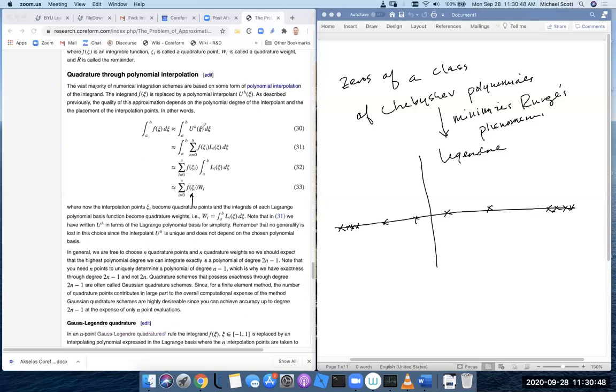Okay, so we normally do this for a phenomenon called locking. So we say, I don't want to lock, so I'm going to pick fewer quadrature points. What it means is you may have picked a finite element basis of degree p. Maybe this integrand is written in terms of some degree p finite element basis.